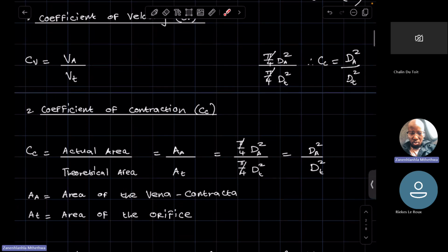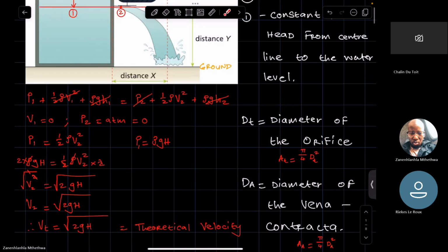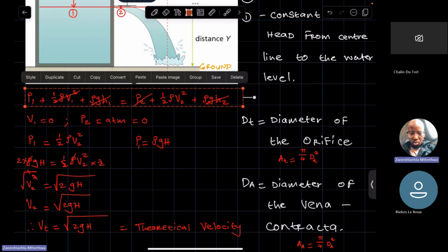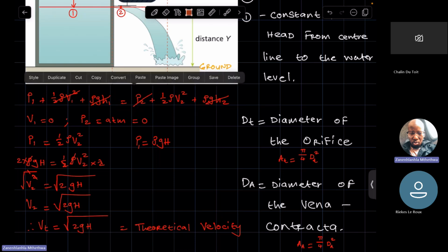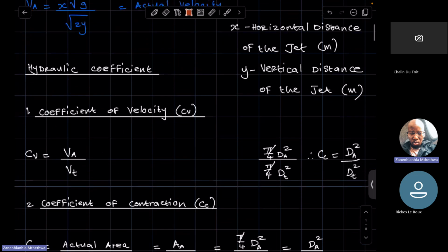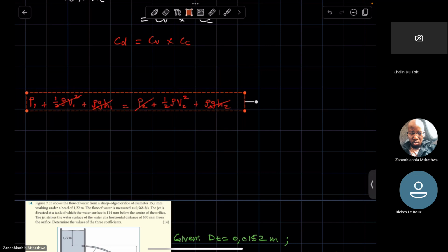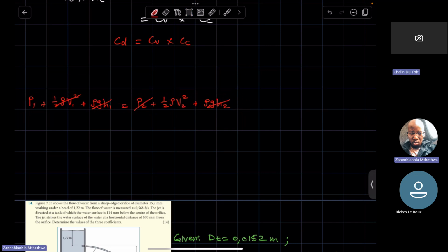Now I want us to look at, if we're no longer looking at applying Bernoulli's from an ideal perspective, how that would affect V2, or how we would then use our Bernoulli's. So say applying Bernoulli's between the same 2 points, but now considering losses. So say we are considering frictional head losses, HF. HF stands for frictional head losses.